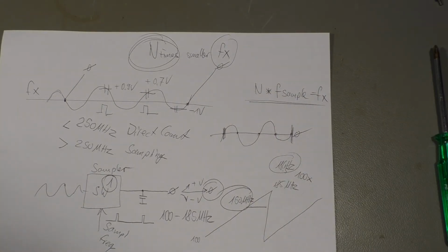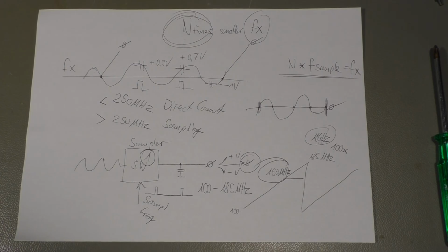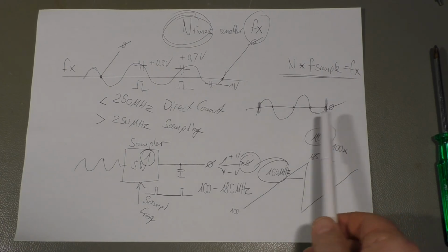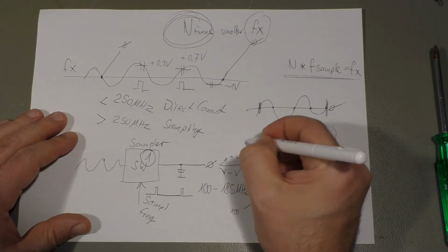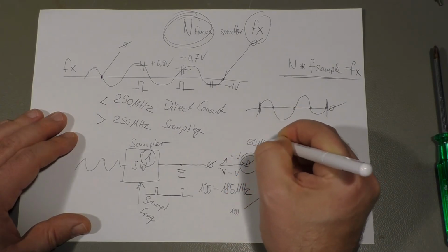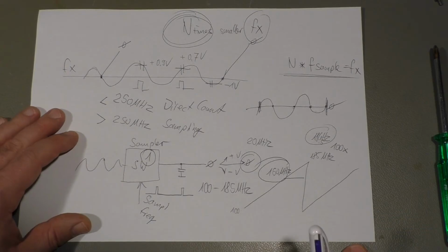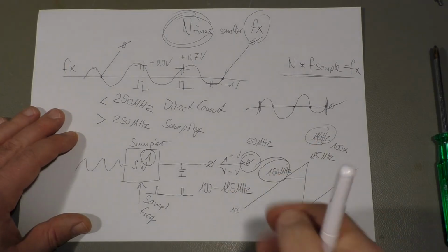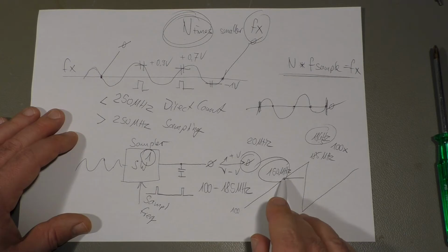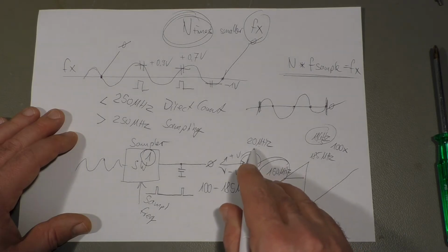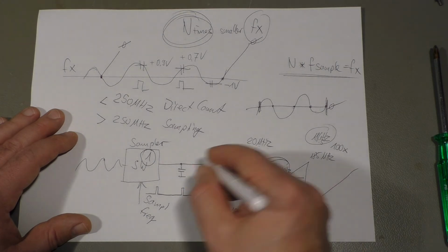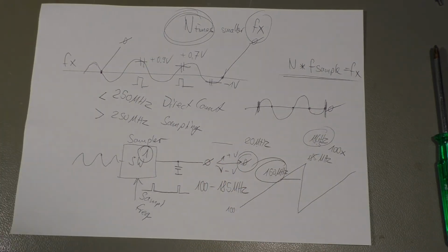Of course, the guys from HP do it a little bit more complicated. They don't look here for a 0 volt, they look here for 20 megahertz. So that's basically the same. You just adjust this frequency here so that 20 megahertz come out instead of 0 volt DC.